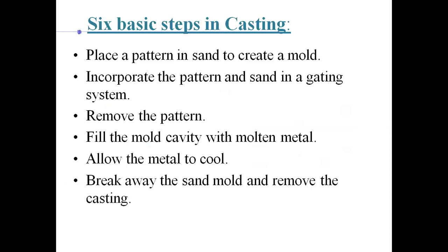If it is to be totally destroyed, then that's called breaking away of the sand mold. Otherwise, if you have made some provisions to remove the casting, keeping that sand mold intact, then you can do that also. So even if you don't remove the core, once you have taken out that component, that core can be removed, right, by hammering. So that is how the core will be removed.